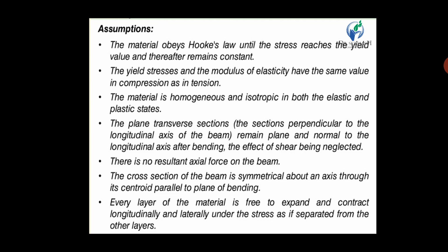Fourth, plane transverse sections remain plane even after bending, and the effect of shear is negligible. The cross section of the beam is symmetric about an axis through its centroid, parallel to the plane of bending. The influence of normal and shear force on plastic moment is not considered. There is no resultant axial force on the beam. The material is assumed to be sufficiently ductile to permit large rotation of the section to take place. And last, no instability occurs in any member of the structure up to collapse.